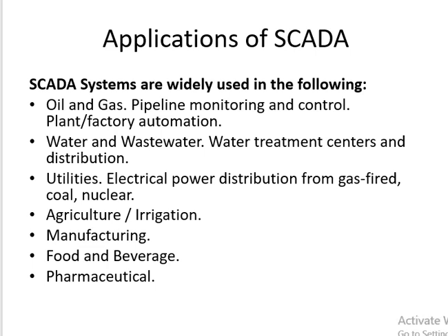It is a method that is used to track or identify an object by radio transmission over the web. Data is digitally encoded in an RFID tag, which might be read by the reader. This device works as a tag or label, from which data is read and stored in the database through the reader, as compared to the traditional barcodes and QR codes. It can be read from outside the line of sight, and it is either passive or active RFID.